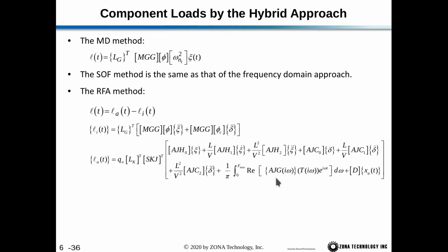And then with the gust, we're going through the inverse Fourier transform here, and once again, we're getting our gust forces on each box. And then lastly, our lag states contribute to the CP on each box. Once we have the CPs on all the boxes, we then pre-multiply by SKJ to convert that to the K-set forces, and then use the LK matrix to integrate those forces.